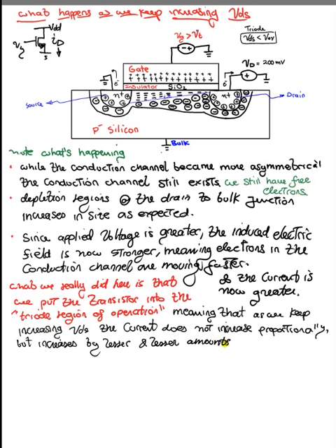I have a little graph here, so it looks something like this. Actually, more like this. There you go. And then you've got VDS on this side, and you've got ID on this side, right? So as you increase VDS farther and farther, the slope is changing. So it's operating non-linearly. Okay, so why?